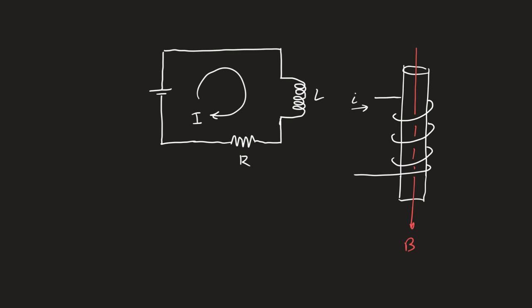So although we can do the capacitor circuits no problem and see the little bulbs light up and turn off and all that kind of stuff, it's harder to do that with the inductors. So all of those circuits that we made first semester, where the capacitor would go and where the current would pass, what's the steady state condition, what's the transient condition, what's the initial condition, it's going to be harder to build those with inductors because of the internal resistance of an inductor being so high. But here's the thing.